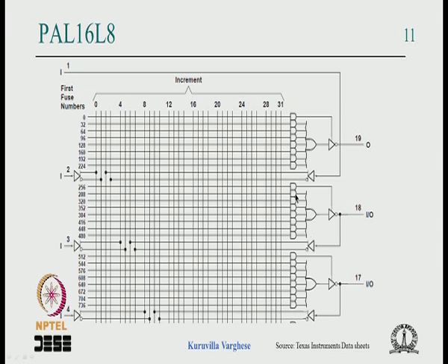So it tells us that you can cascade. You can have 7 product terms implemented in this section, say the output is inverted, but it does not matter, it gets the second inverter, there is a buffer in this line, inverter in this line, and from that inverter you get that signal, and that can be connected to this first AND gate here, okay. So you get 7 product terms in this OR gate, you implement suppose 3 additional product terms in this section, so you get 10 product terms. So when there is a need for more than the product terms accommodated in one section, you can use this structure to cascade to get more product terms. So that is an additional use of this particular structure.